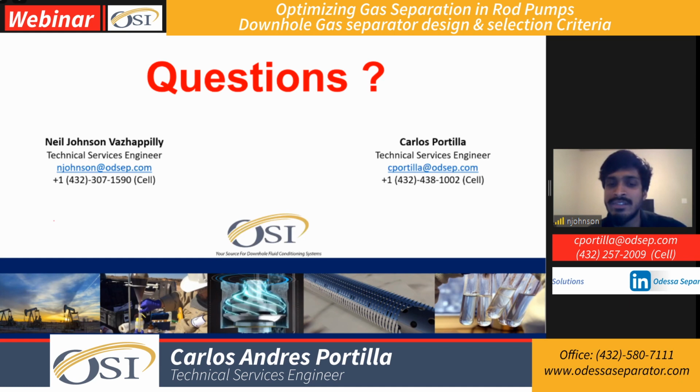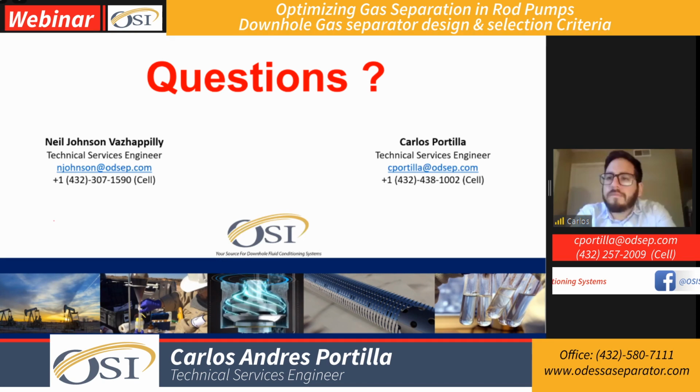But since there are some similar chamber type separators in the market, you all can take a look at one of the limitations that it can have. That is basically having the opening of the dip tube in multiple chambers. We need to make sure that that's calculated and divided the way it's supposed to be, so that the total pressure drop is taken into consideration if we need a chamber type to work as a chamber type separator. Correct. Perfect.